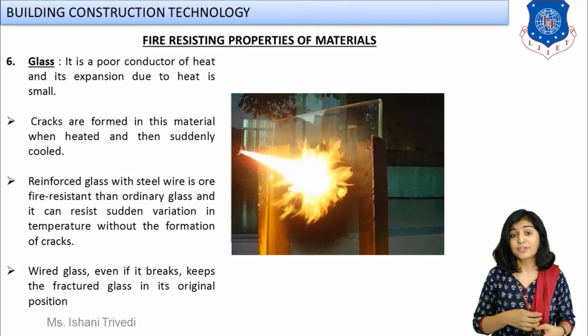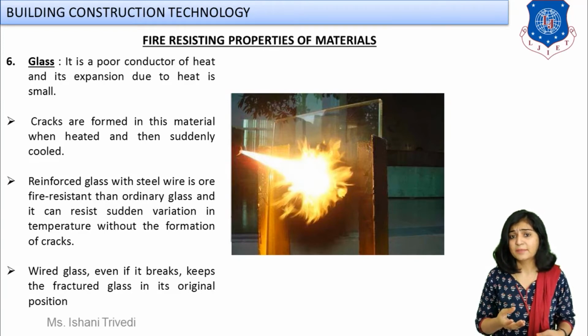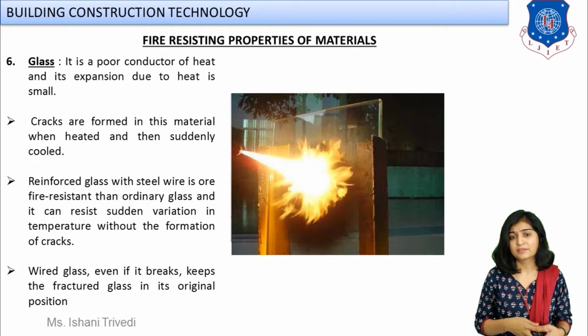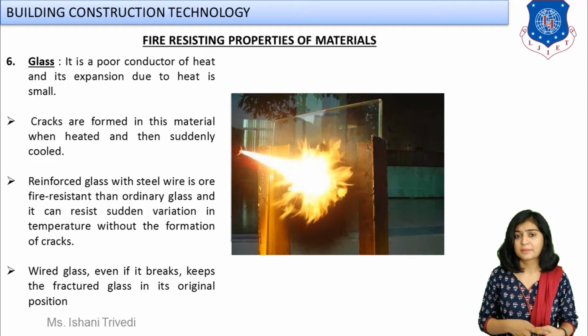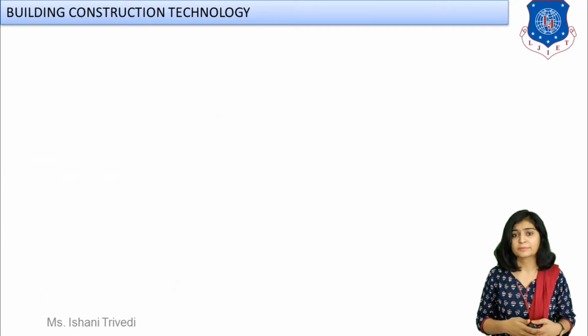As I told you already, you can make fireproof glass, which is under experiment, but cracks are formed in this material when it is heated, just like stones. When it is heated to a large extent and immediately cooled down, then cracks can be formed, but it cannot completely blast under these effects. Okay, so students, this covers fire resistance in buildings, the type of special treatment which has to be provided, which is ultimately provided in the design of your structures.